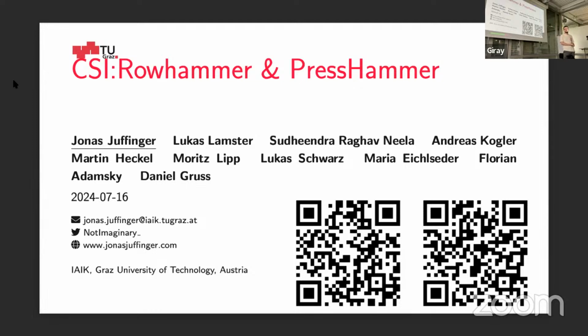I think with DDR5 they could do it, right? They have the voltage converters on the board, so they could actually modify the voltage quite directly based on aging. I think so. You can also use ECC as a canary, I guess, because you detect how many bit flips happen, right? Yes. You can reduce the voltage until you see bit flips, and then you can stop reducing. Exactly, and then you could also do this dynamically, I guess. And as a system on a chip, you control the DRAM voltage, so it accounts for aging.